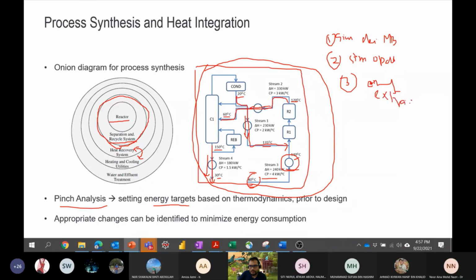Number three, extract the data. Once we get our simulation model closely matching the current situations, we can use the results as the data source. So for example, if we don't have the temperature measurements over here, by using the simulation data, we can use the temperature calculated over here as the outlet temperature. So this one now we can use in our further heat integration study. So that's what we did.